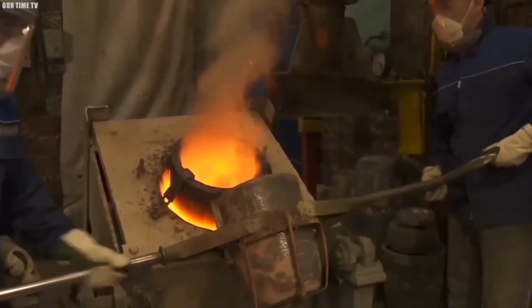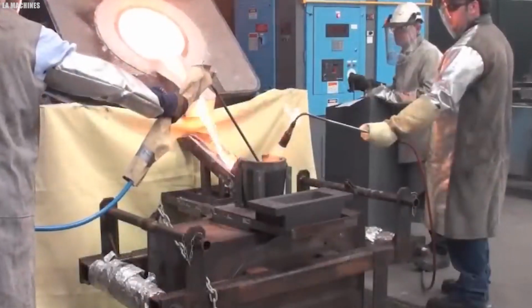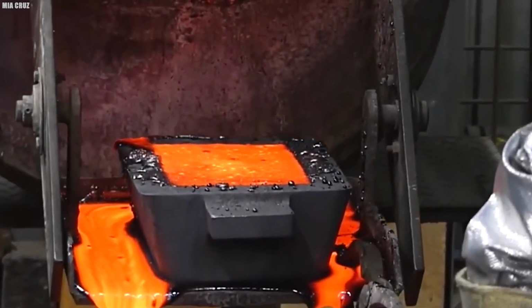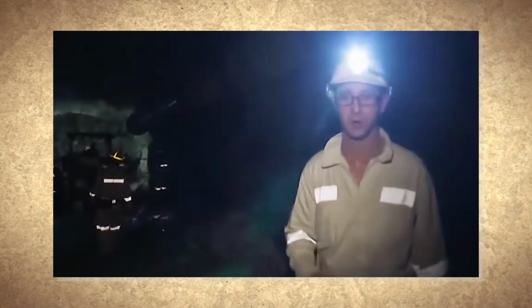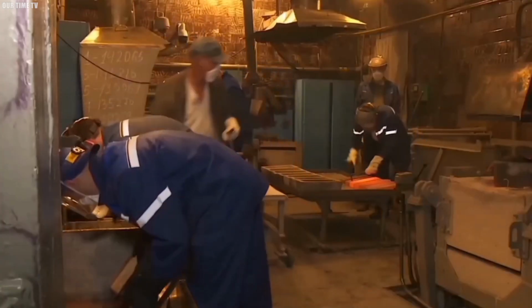Safety measures extend beyond environmental precautions. Mining personnel receive rigorous training on handling cyanide safely. However, one may ask, aren't there alternatives? While cyanidation remains dominant, alternative methods like the carbon-in-pulp process offer valuable insights. In this method, activated carbon particles are added directly into the leach tanks, where they absorb dissolved gold from the slurry. This eliminates steps involved in conventional cyanidation processes and enhances efficiency.